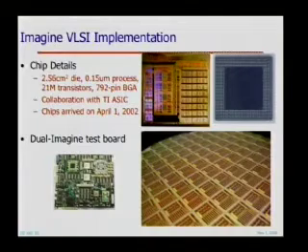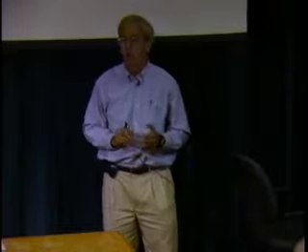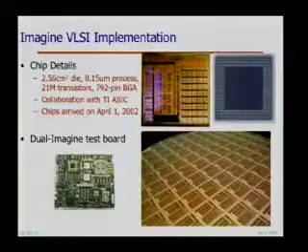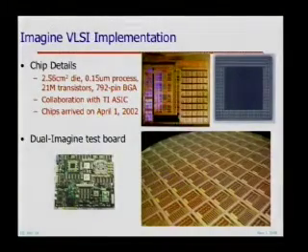And they worked. And one thing that we did is we benchmarked them against an NVIDIA chip of the same era with the same transistor count, also in a 0.18 micron process. And it was a dead heat. I think they beat us on fill-limited things, and we beat them on vertex-limited things. But we were very close to the performance of hardwired graphics processors. But by the way, there was also a ray tracer built to run on this, and a subdivision surface rendering algorithm, and a bunch of other things, as well as a UMTS modem, several video codecs, and some image understanding algorithms. So you had the flexibility of being able to program arbitrary things, and yet you were matching the efficiency of things that were hardwired.